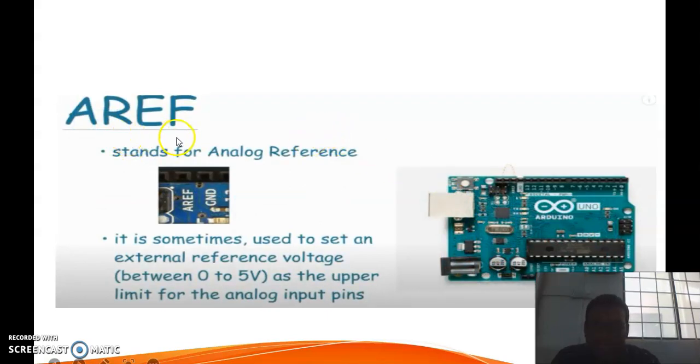The next one is AREF. It stands for analog reference pin. It is sometimes used to set an external reference voltage between 0 and 5 volts as the upper limit for the analog input pins.